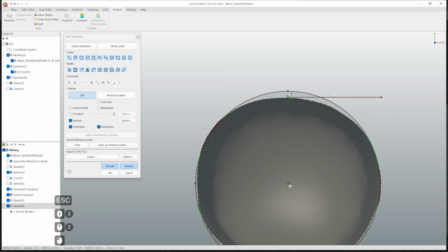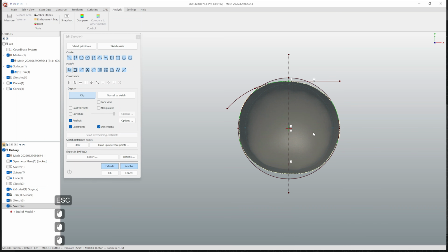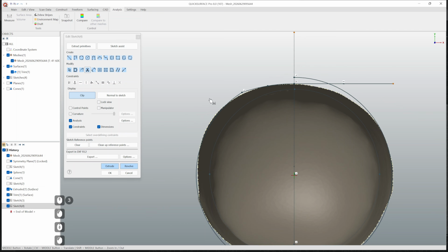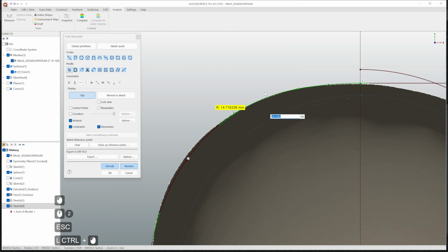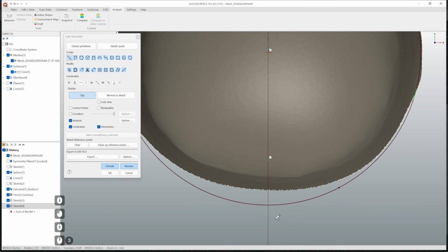Then I'm going to use a tangent arc to fit the top part of it, so I can see it doesn't bend good enough to complete all the shapes, so I'll just do that in parts. At this moment I want to create a vertical axis here, so I will trim this whole sketch later and just mirror it to the opposite side. Okay, from here I can trim the circle, trim the tangent arc, add a calculated radius to this corner, and I want to do the same here on the bottom side.